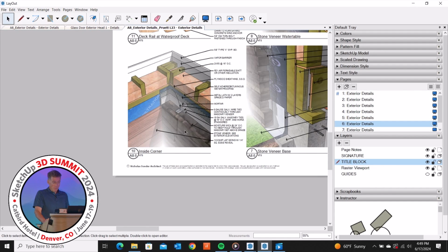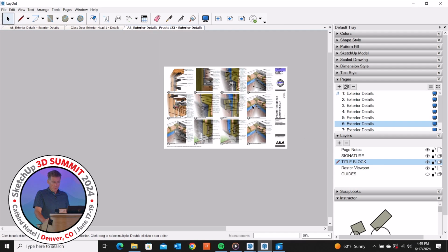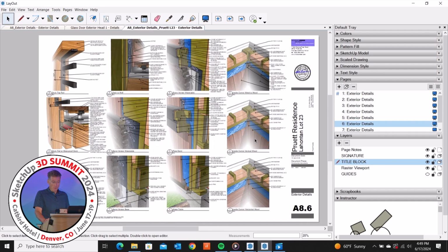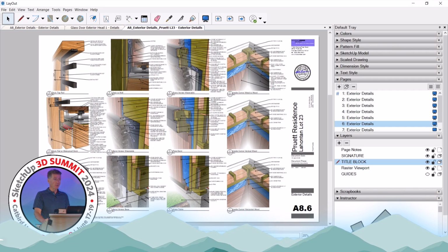And more details again of inside corners and how those are treated, especially when we have transitions of materials. I only transition materials on inside corners, never on outside. And so I'll have each condition where that occurs. If you see one out of place, that's because I went through the drawings and went, oh shoot, that one goes there. Yeah, and then there'll be various exterior trim details, you know, the different water tables that we have,